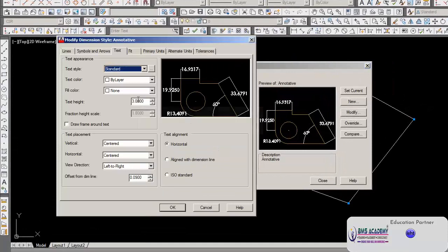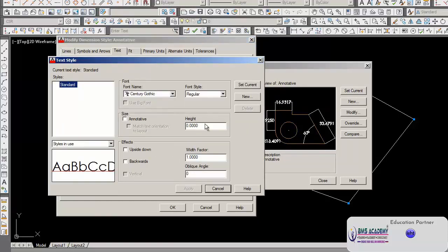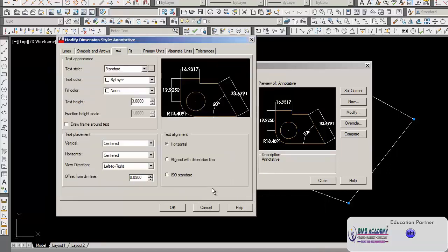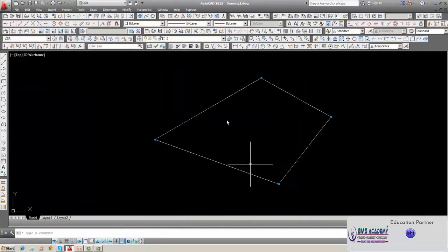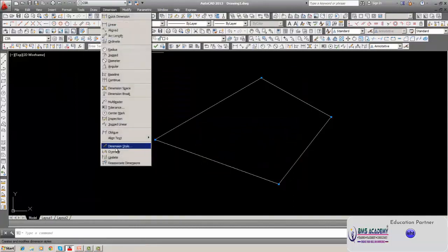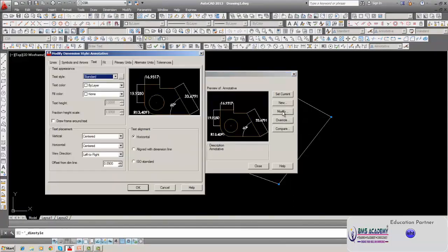See here, it has come back. When I have set it to 0, here I can modify it to 6, 2.5, anything. Once you set a value there in the standard scale size, you cannot modify it. Suppose I set it as 3. It takes a value of 3, and you cannot change it now. You can change it now, but you cannot change it once you reopen. I will open once again. See, we cannot change it, so we have to go there and change it.